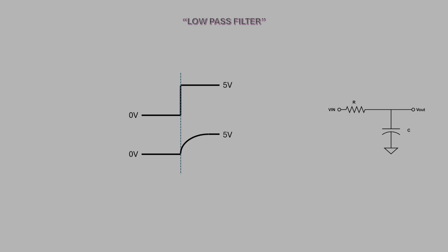So when we apply a DC source of 5 volts at the input of the RC filter, it is going to assume that the step has happened at t equal to minus infinity, and it is going to return the settled value as the DC operating point.